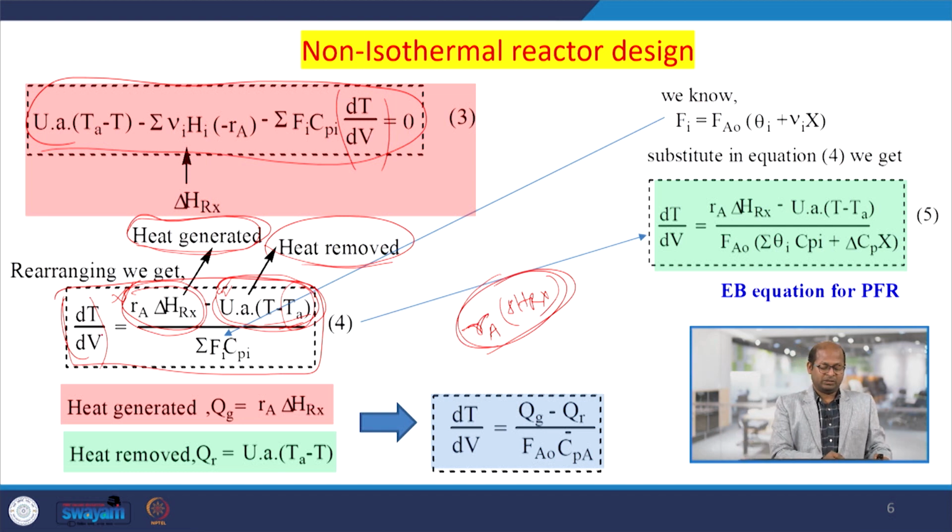So, this way it is balanced, the temperature inside the reactor: one way, from the reactions heat generation should be there, and from the coolant or heat exchange medium, the heat would be removed from the system. That way it would become a steady state and equilibrium would be there, and the system will run throughout the operation, for let us say 5 hours, 10 hours, 20 hours, maintaining a similar pattern of temperatures along the length of the reactor.